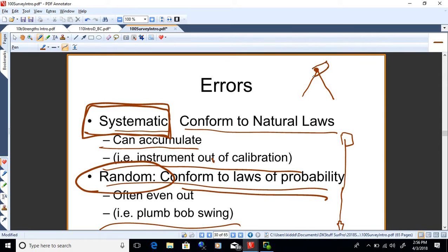And if you're surveying, you hear all kinds of stories about this stuff. The guy I worked for, they were shooting an angle and they couldn't get the thing to check properly. And they were shooting near a tree. Here's the tree root that just happened to go under the instrument. When they turned to get to that angle, they were stepping on that tree root every time they went over. That tilted the instrument a little bit and kept throwing them off. They couldn't figure that out, but eventually they did. So all sorts of these little things come up.